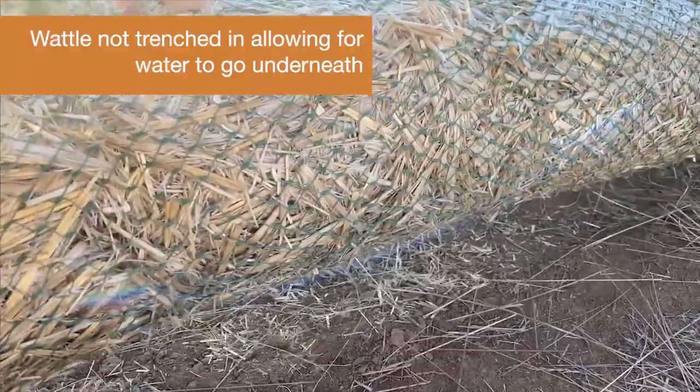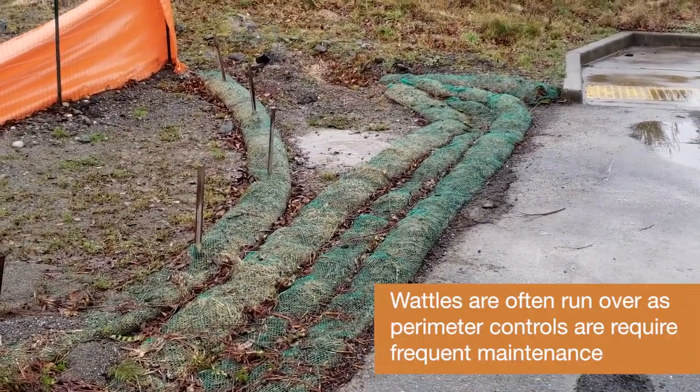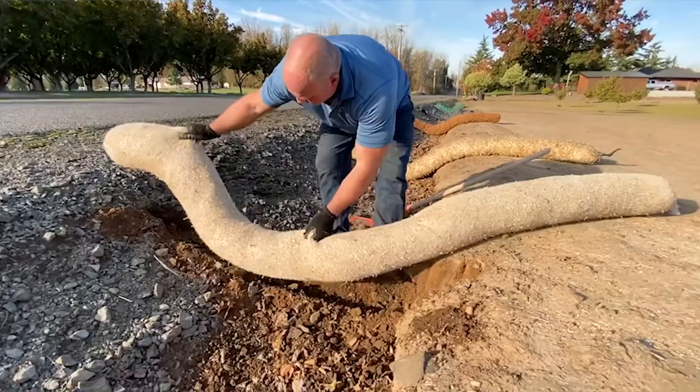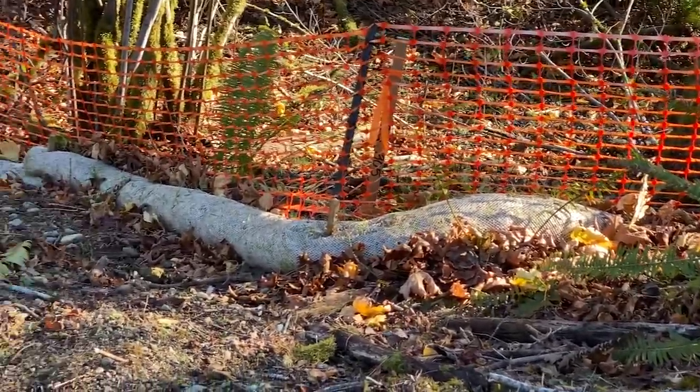So just like sediment fence, you need to create erosion to prevent erosion by trenching in a wattle. In other words, you need to give it a 2 to 3 inch little nest for the wattle to sit into in that pocket, and then backfill the uphill edge of that wattle.